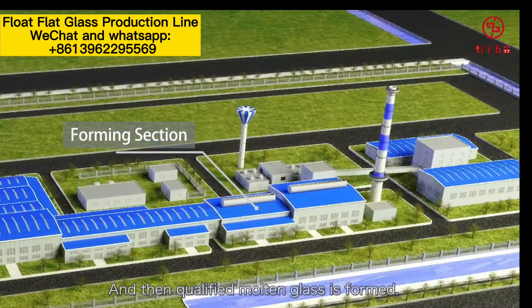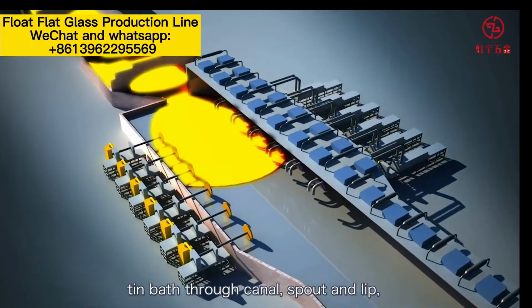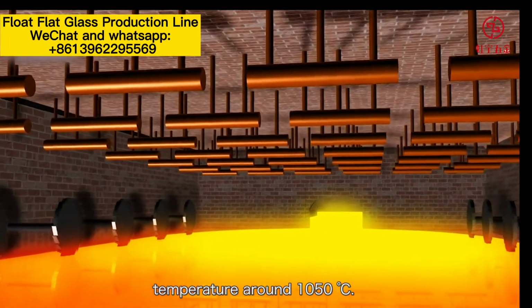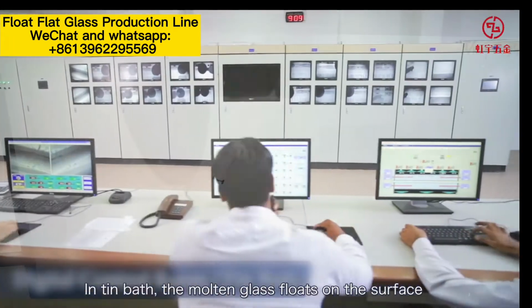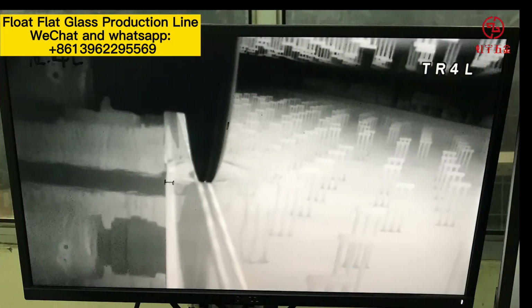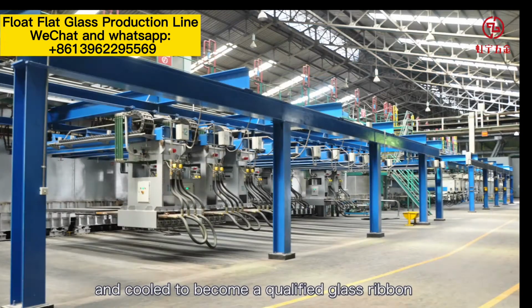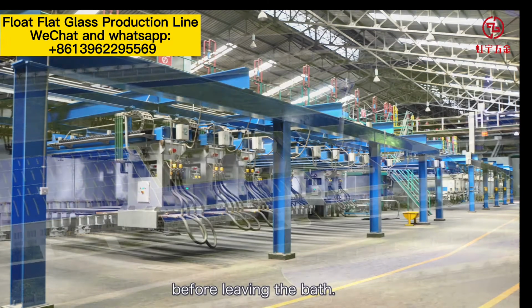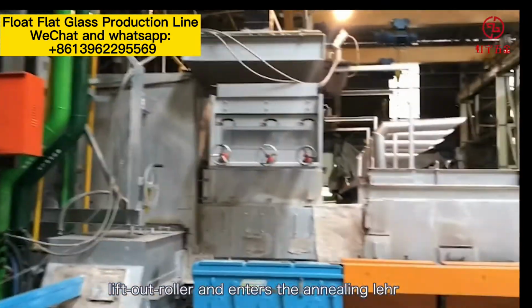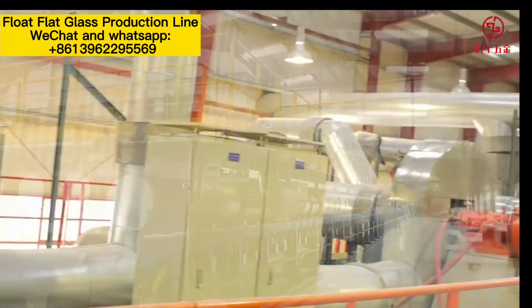In forming section, the molten glass flows into tin bath through canal, spout, and lip, and there the glass ribbon has an inlet temperature around 1,050 degrees Celsius. In tin bath, the molten glass floats on the surface of the tin liquid to be flattened, polished, thinned, and cooled to become a qualified glass ribbon before leaving the bath. Afterwards, the glass ribbon passes through the lift-out roller and enters the annealing layer at a temperature of about 600 degrees Celsius.